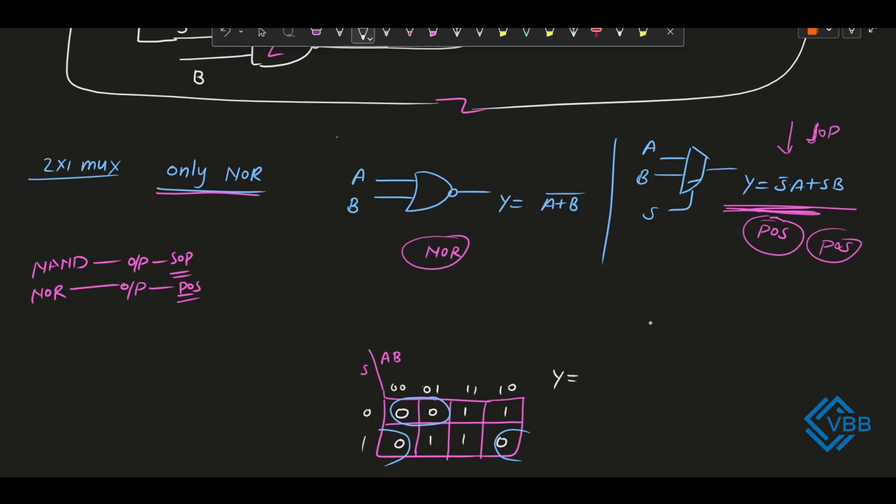So what will be the output from this KMap? That will be S, A, because S is coming from this side and a common part from this area. So what is the common? A. So what we will write here is S plus A, and this is the POS format. After this the dot will come, and next we write the next term.